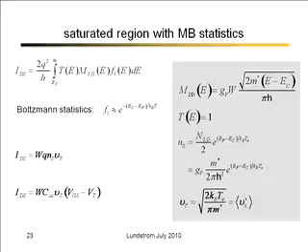The charge in the channel is related to the gate voltage by Cox times (Vg minus Vt). That's all there is to it. Now I have an expression for the on current. There's one kind of curious thing that I've done that I should discuss just briefly.